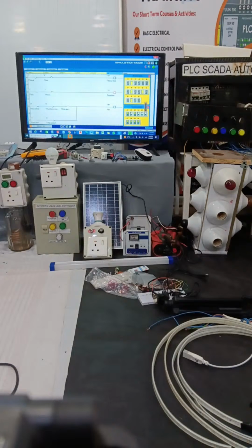Now still some further loads are stopped, so we need to switch off the 15 kVA capacitor. So the controller will give a command to open this contactor. By this we can automatically switch off all these contactors. So now all are switched off. This is how the controller works.